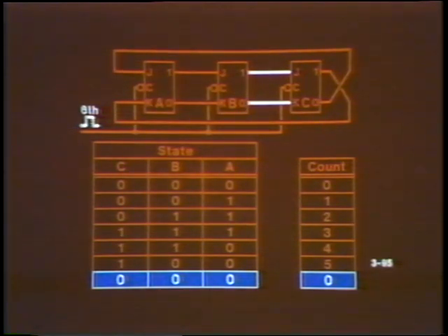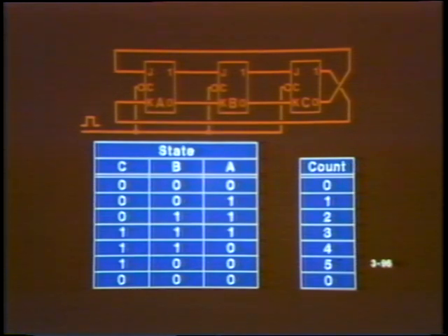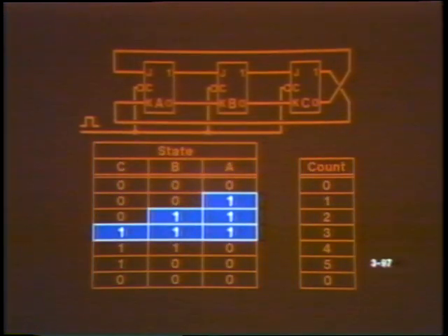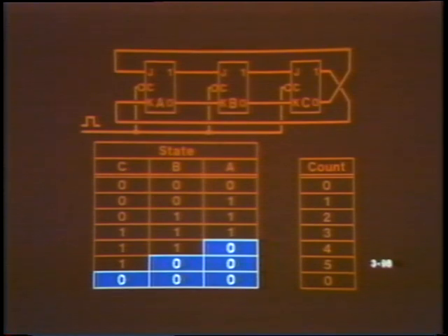This counter has 6 distinct states. Notice the sequence in which these states are occupied. 3 states represent a progression of 1s, starting at A and moving right 1 flip-flop at a time. Then when all flip-flops are set, the switch tail feedback loops cause A to reset, and a progression of 0s begins, moving 1 flip-flop at a time, just as the progression of 1s did.